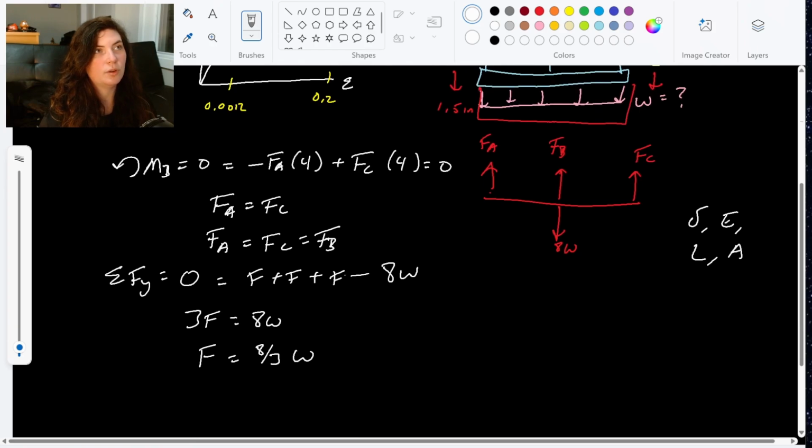I was able to, from the statics and from looking at it, simplify some things down. Instead of having these 3 unknowns, I have just 1 unknown plus the W, right? So 2 unknowns. So instead of having 4 unknowns, I actually just have 2 unknowns, the F and the W. Since all of my forces are the same here, it's perfectly symmetrical, moving down through the same displacement.